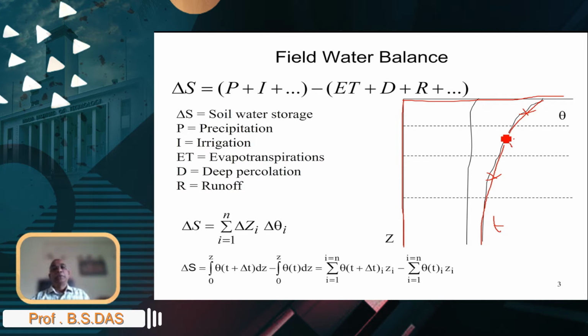Then, if you come back tomorrow and look at the soil profile, and for any region there is a change in the soil wetness, you are going to see a different soil water content profile. The loss of water from this profile is going to be this difference in the soil water depths, which you can calculate using our concepts of equivalent water depth.